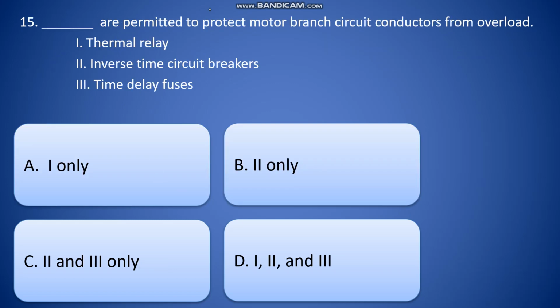Blank are permitted to protect motor branch circuit conductors from overload. 1. Thermal relay. 2. Inverse time circuit breakers. And 3. Time delay fuses. I guess all.